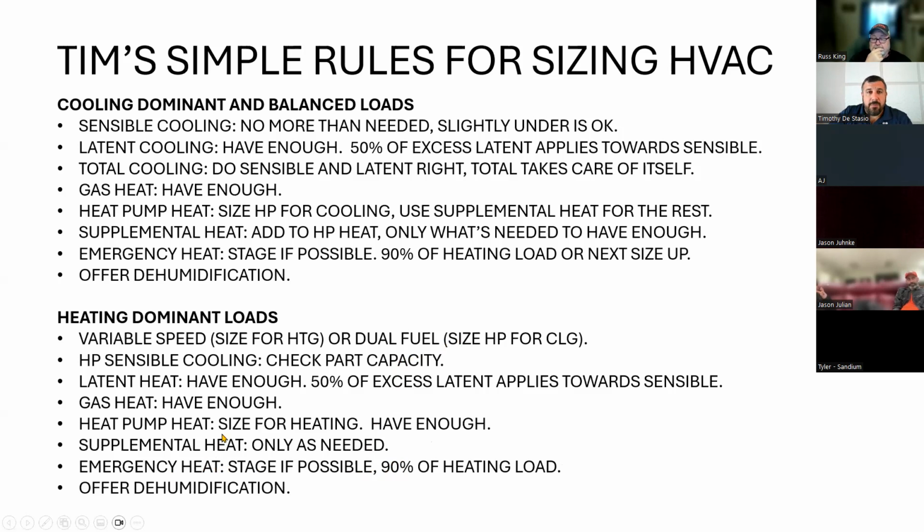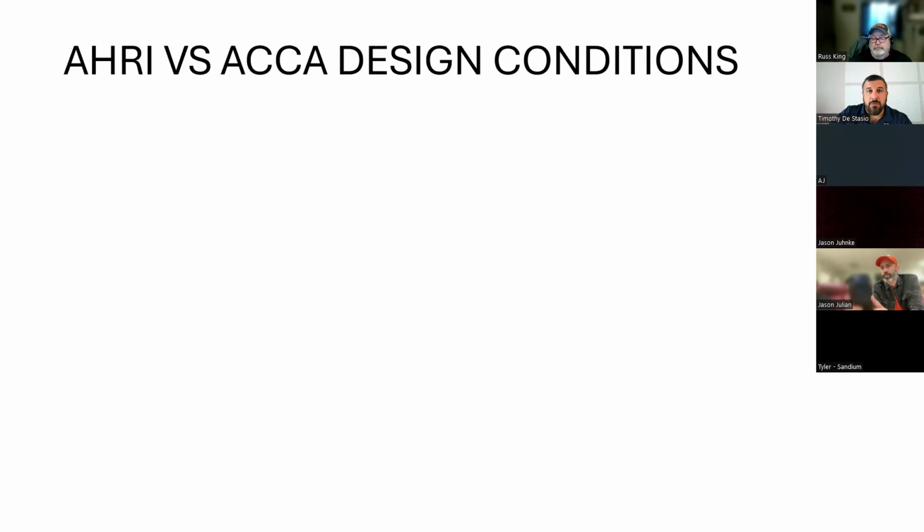Offer dehumidification, because chances are your cold climate heat pump will not be able to turn down enough to handle the latent load, or as we'll see in a future slide, they do not publish their latent capacity at those conditions. And so you have no idea what it's going to do. And in that case, you need to offer a dehumidification to protect yourself.